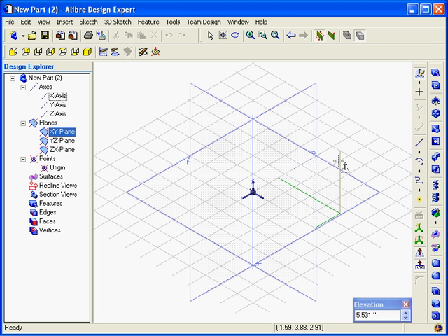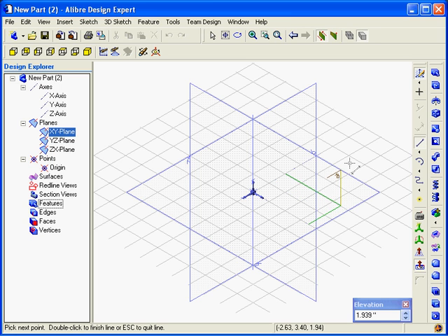If you are in a feature creation command, such as a line figure, you can change elevation by pressing the E key on your keyboard and holding it down while you place the figure. To demonstrate this, I will first exit Elevate mode by selecting the tool again. Then I will select the Line tool. Notice the guidelines appear when I am sketching a figure. I left-click to start the line and drag the cursor to sketch it. Left-click again to place the endpoint.